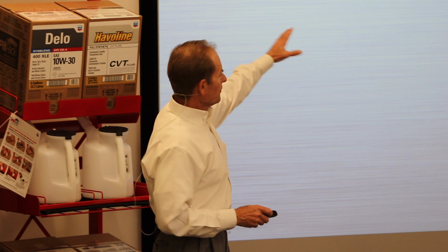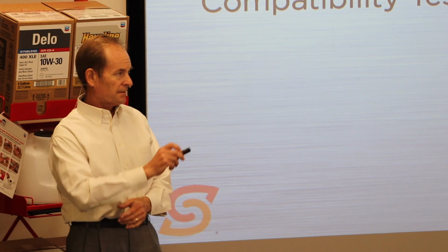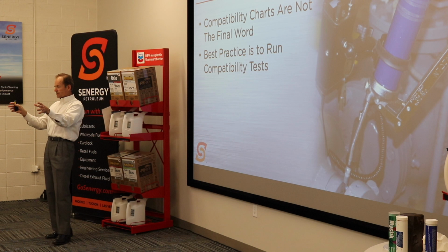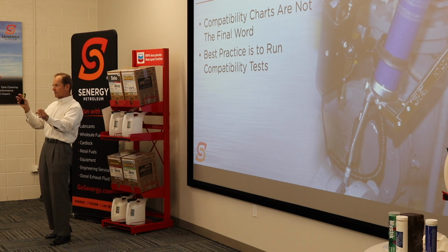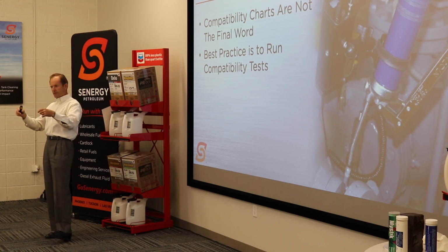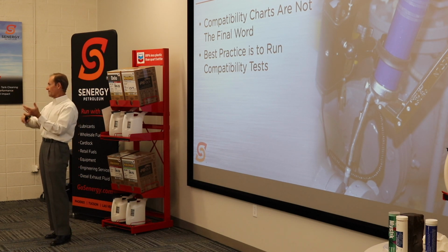So my thoughts on compatibility charts, they're not the final word. Okay? They're a good guidance, but they're not the final word. And the best way to do this, if there's a question about this, is to run compatibility tests. Compatibility tests are pretty straightforward. You get your two greases, you mix them up in 75-25, 50-50, and 25-75. 3 different proportions.